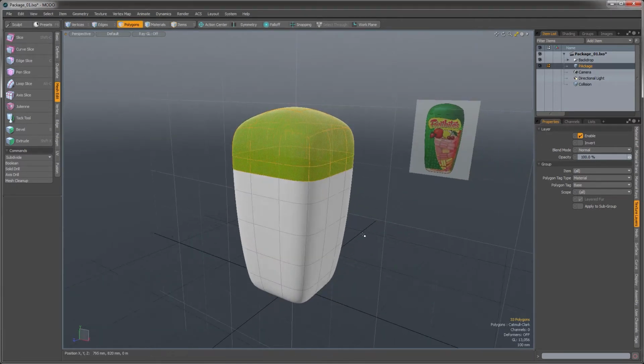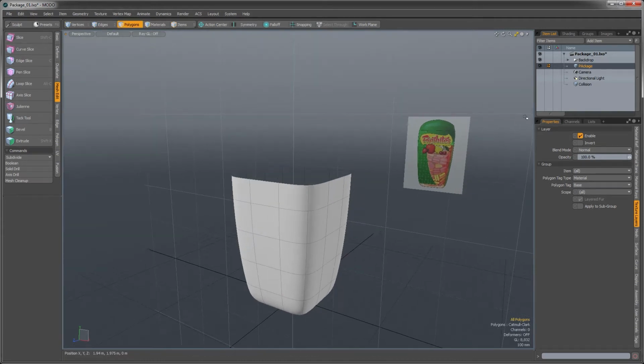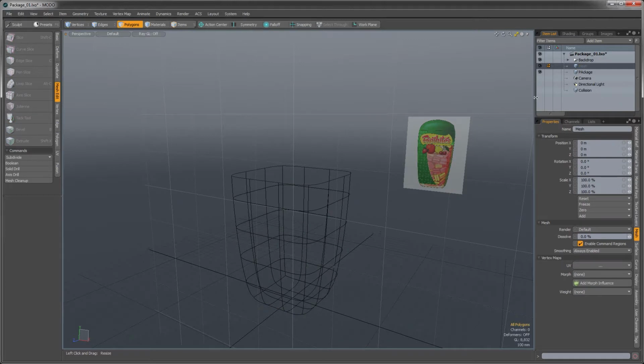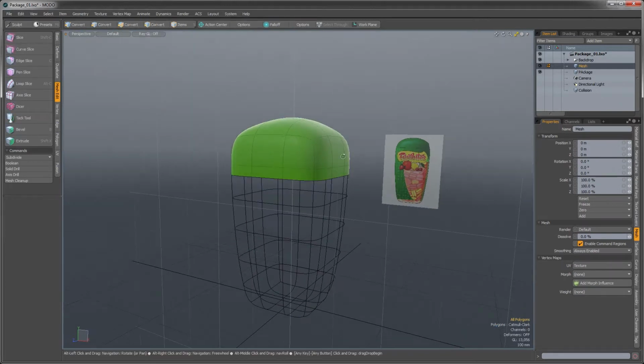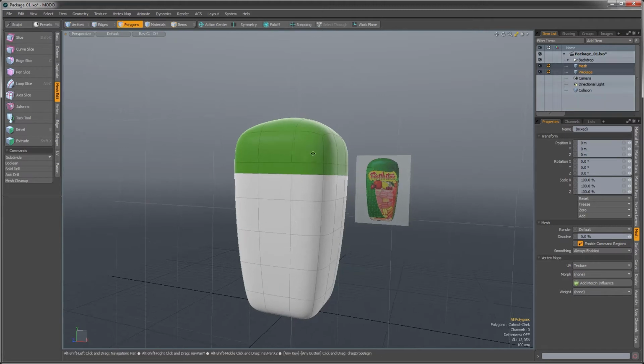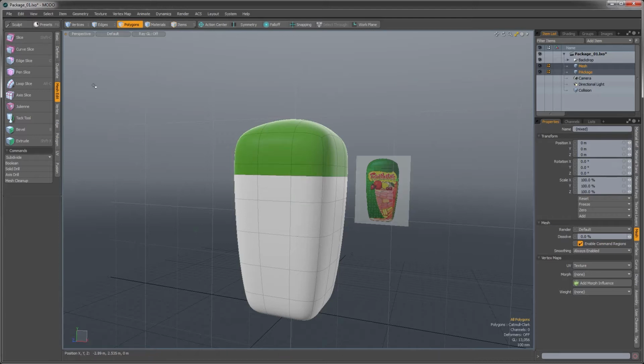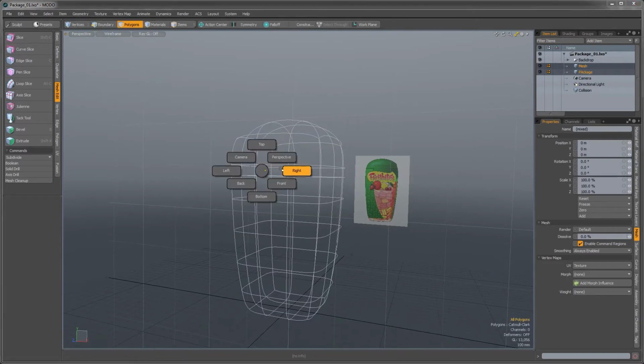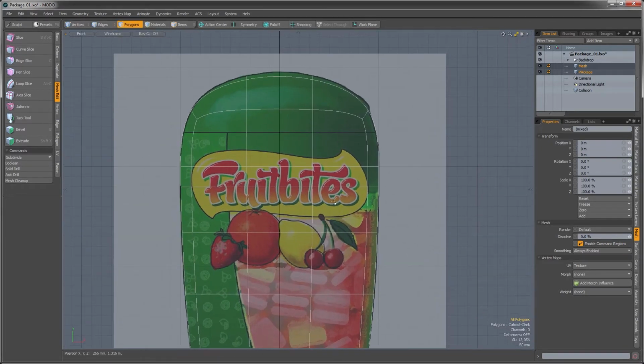All right. So let's Control X to cut those out. Press N to create a new layer and Control V to put that in there. Now with both layers selected, we want to make sure that this seam ended up at the same piece, because once you cut them apart, it changes the tension that sort of runs across the subdivision surfaces. So let us make sure that we don't need to adjust that.